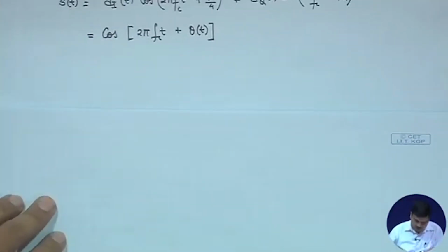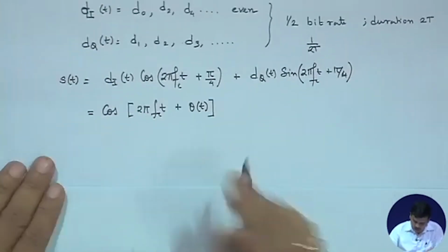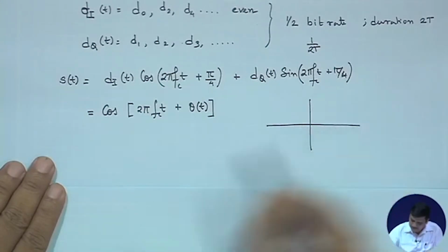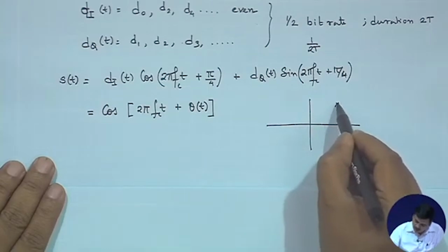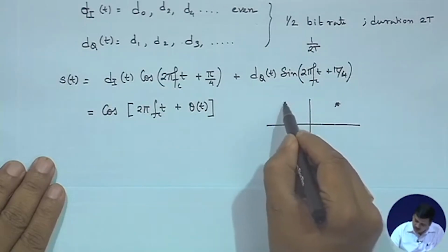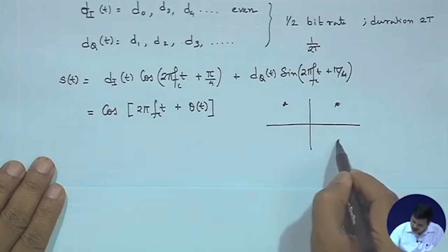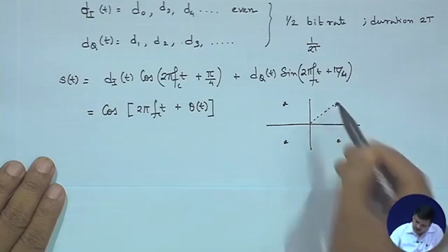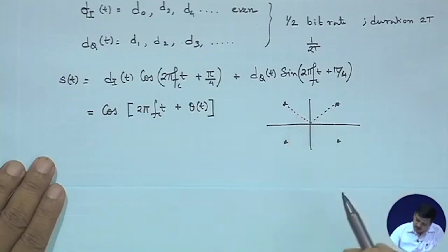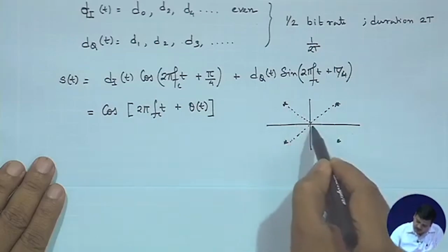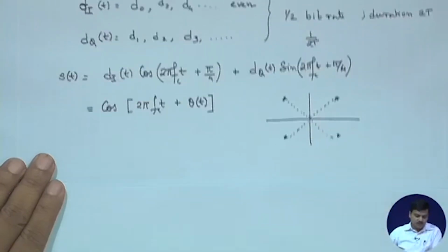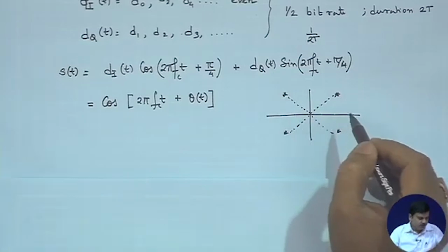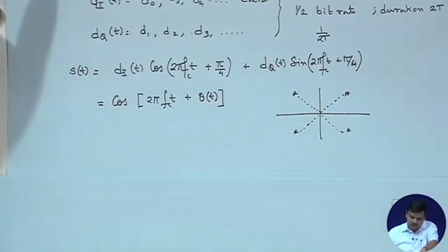We can use this space itself, and you could say that you have used these locations as constellation points: pi by 4, 3 pi by 4, minus pi by 4 and minus 3 pi by 4. These are the 4 phases that you have of a cosine. So, you would select any of the 4 phases that you would require for transmission.